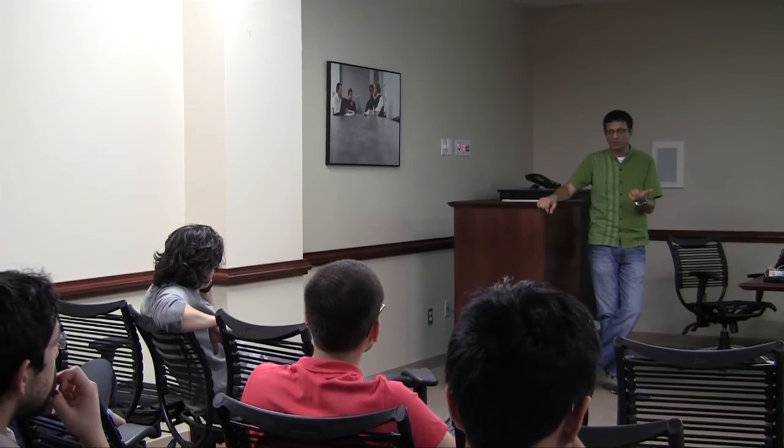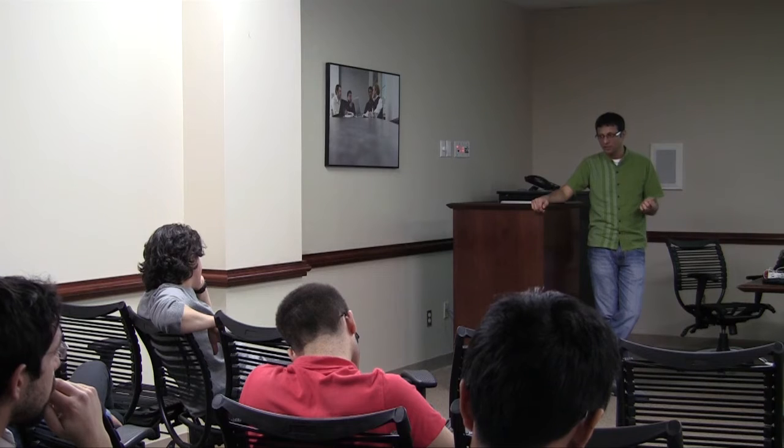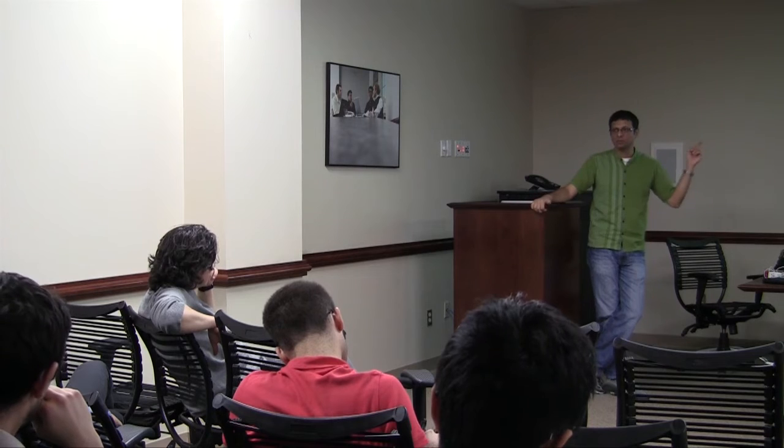The reason why we want to train as fast as possible is because the coherence time is fixed, and it's, let's say, a small number. So suppose you have, say, 5 antennas and the coherence time is only 40 symbols. If you take 5 symbols to train, then 5 out of 40 symbols get lost in training itself. So what we're trying to say is you can achieve a better diversity multiplexing gain trade-off if instead of using 5 symbols to train, you just use 1 symbol to train, but you exploit the beamforming vector which is already available. So this is like transmitting a training signal simultaneously from all the antennas, but using the beamforming vector as a kind of gain applied to each antenna.